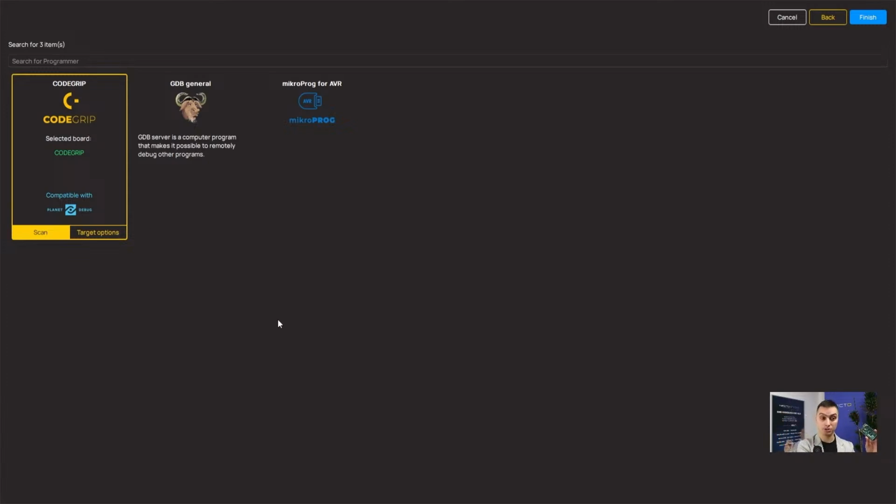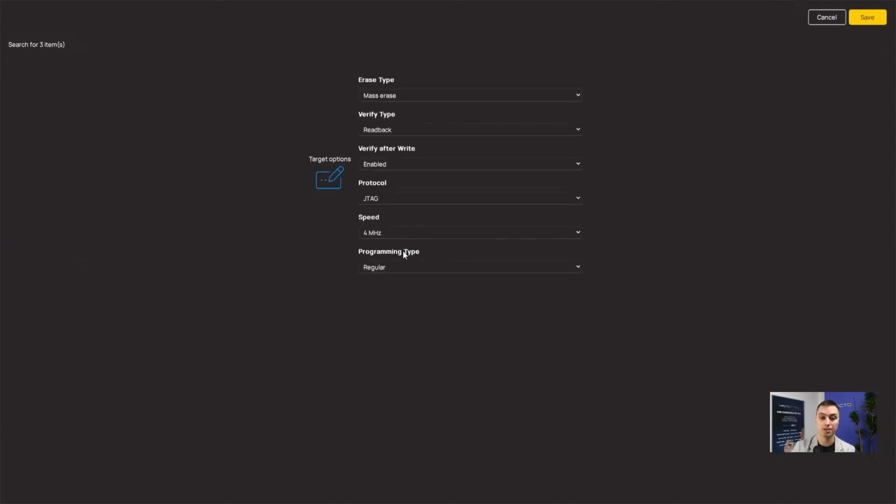So please make sure to jump into target options over there and to select the in-circuit programming as the default programming protocol, and after that I would stick with the 2 MHz speed of programming. I will not need the verification after we have written the code into my controller, because this is a webinar session and the verification can last a little bit, so I do not want to waste your time. So this is why I'm going to disable the verification.